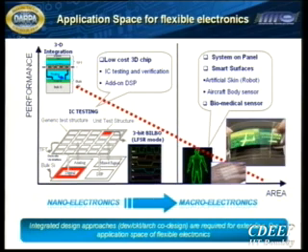But if you really look at most of these transistors, and today they are certainly used, the TFTs are used in any one of these displays. They probably work with 10 to 15 volts, and they're not very good transistors. They're actually pretty bad transistors.